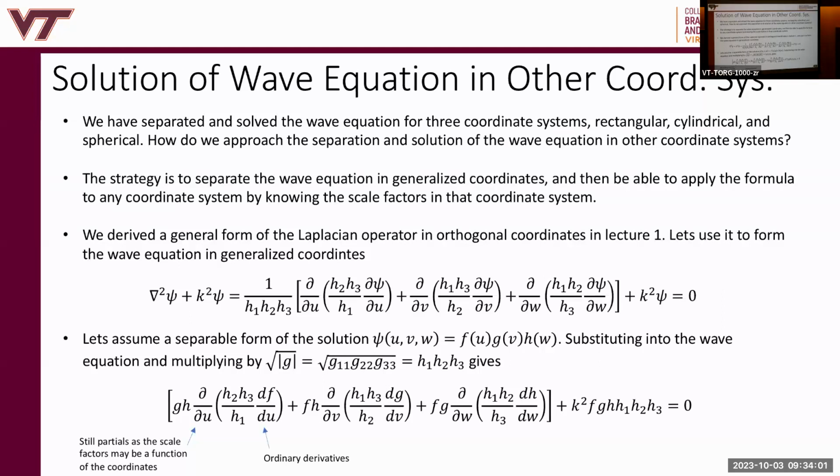You could have E phi or H phi. In that sense, you'd have to solve for the Z-directed magnetic vector potential. So you'd expand the vector potential. It has to be a Z-directed component or quantity. So you expand the magnetic vector potential, then you take the curl of it and so forth.